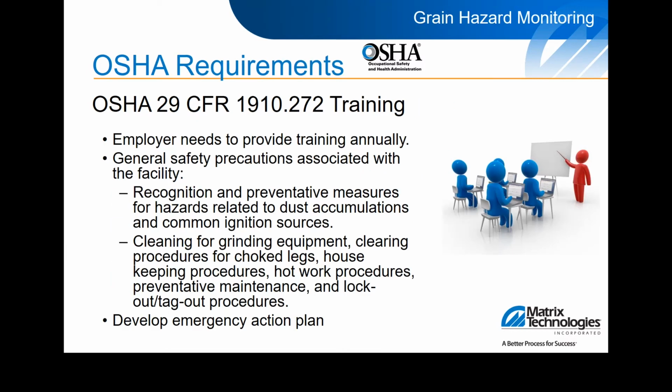Employers are required to provide annual training around the hazards involved with grain handling. Typically, this is provided in annual site safety training refreshers, but can also be obtained via outside sources such as the Grain Elevator and Processing Society, GEAPS, Feed & Grain Magazine, and/or equipment manufacturer presentations. Topics to include for training are recognition and prevention measures for reducing hazards due to dust accumulation, how to properly clean equipment, clearing choked conveyors, preventative maintenance, and lockout-tagout procedures.